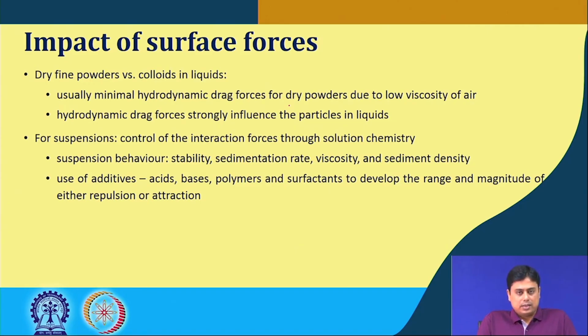Now, for a colloidal suspension or fine particle suspension, we can control the interaction force through the solution chemistry that dictates the suspension behavior. What is the suspension behavior? That is, its stability, sedimentation rate, suspension viscosity, and suspension density.